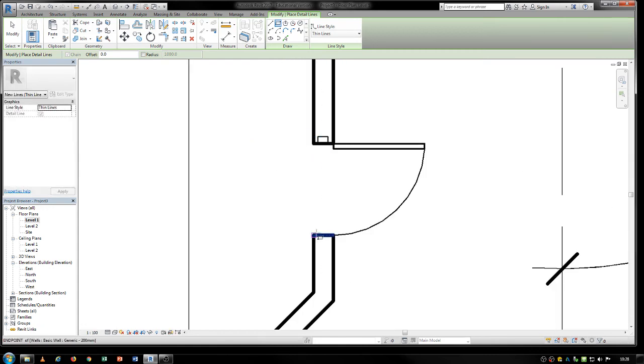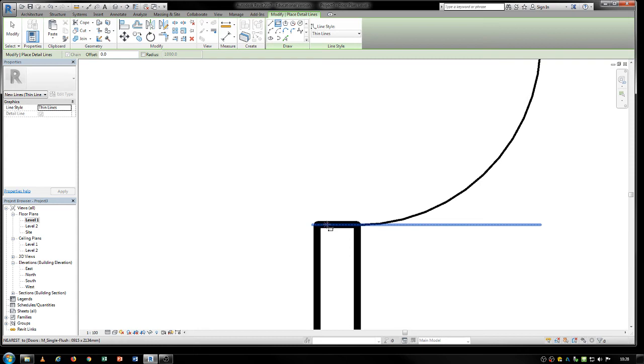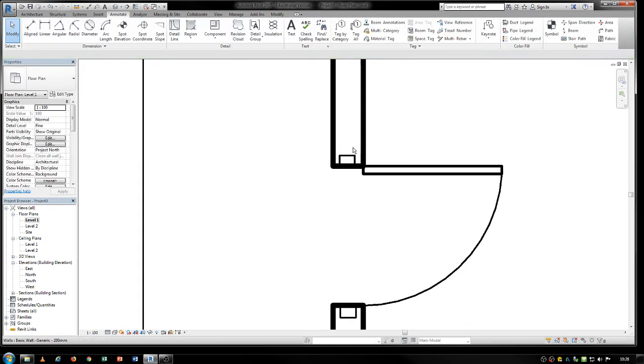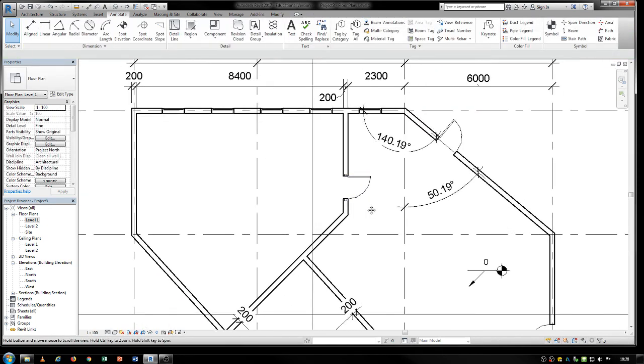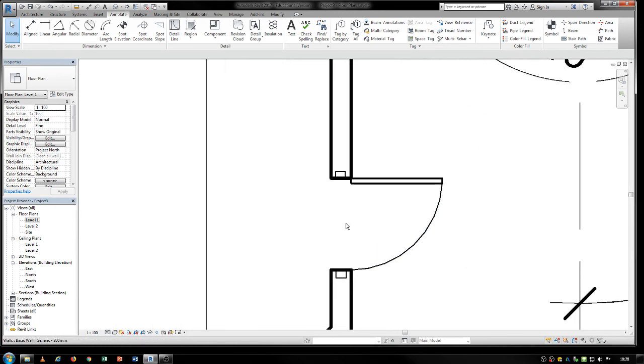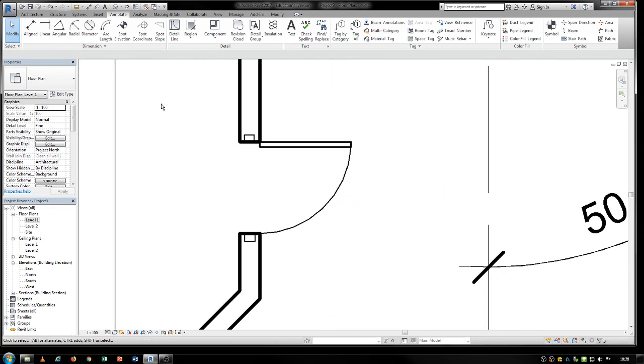That's kind of referring to the frame of my door. And similar to other stuff in Revit, you can control the dimensions and alignments and everything. So you would draw a few things here, but it's not going to show up anywhere else. It's not going to be actually in the model. It's only in that certain view that you're playing with at the time, and it's only for showing some details that are not modeled. Next thing is a region.